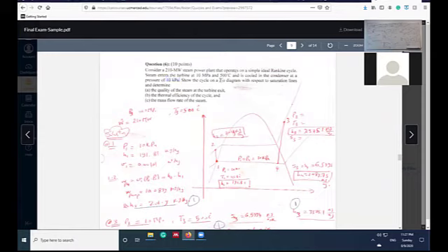Show the TS diagram. I can ask for the show PV diagram, something else, but very similar with respect to saturation lines. Yes, this is the saturation lines and this is the PV diagram. Determine the quality at the turbine exit here. Give me X4. Thermal efficiency, 1 minus Q low over Q high. The mass flow rate, because he gives you the power, and you can get the power per unit mass, you can get the mass. Let's go step by step.